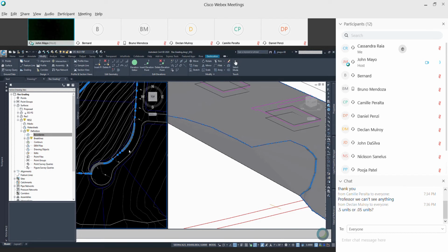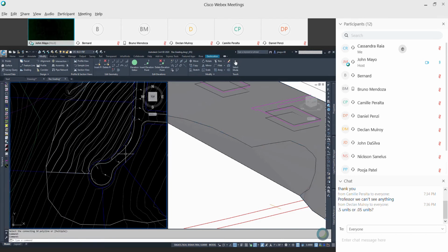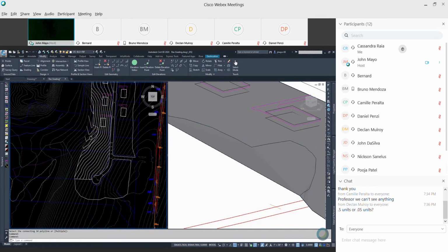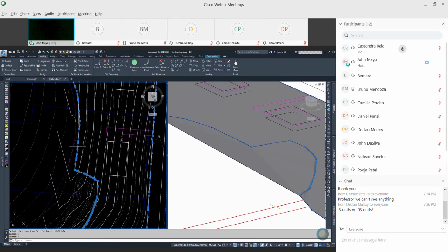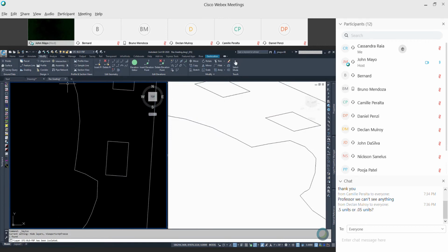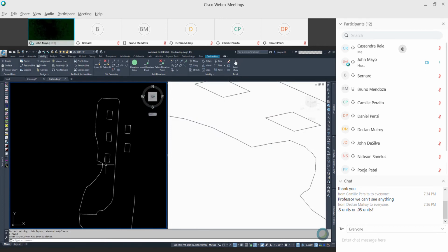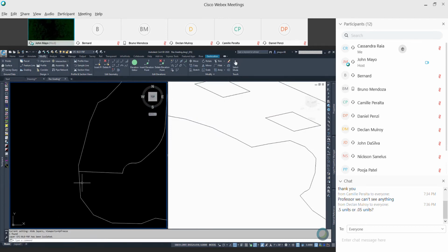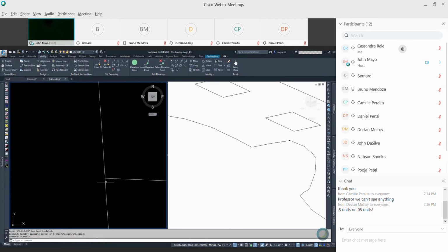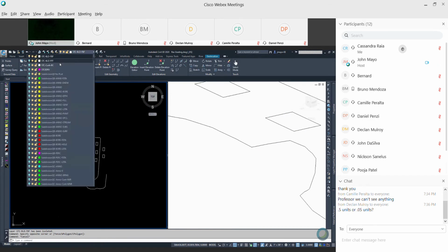And you got to have good geometry. I have a crossing in there somewhere. Somewhere on this polyline overlaps itself. We might be able to fix that by going to layer 0 temporarily, putting it on and making it current.